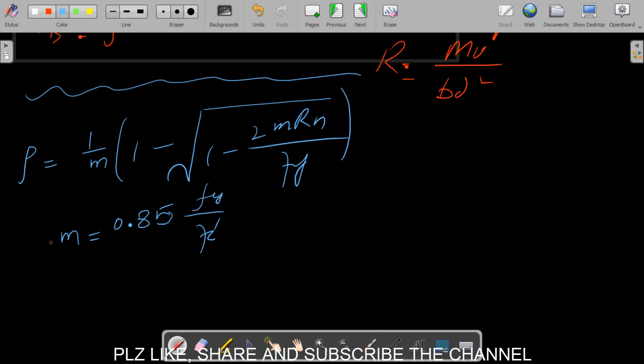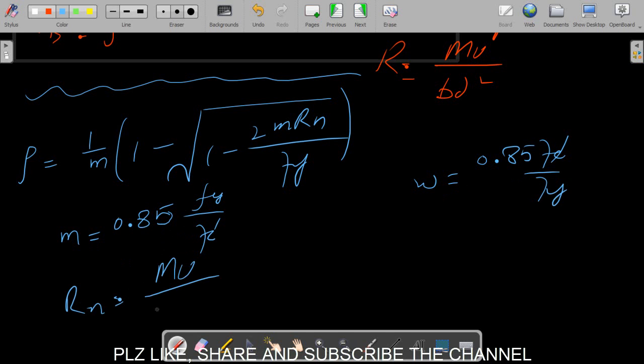Here m is changed from omega, because omega equals 0.85 fc prime divided by fy, I think so. This is omega, but here m is 0.85 fy divided by fc prime, and Rn, also noted by R, equals Mu divided by phi bd square.